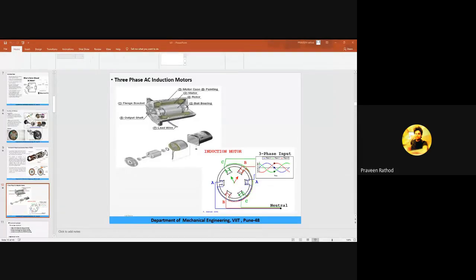Typically a small-sized, high-speed, low-torque motor together with a single-speed, high-reduction transmission can be used. This single electric machine can be used over here. What is it helpful for? It helps in reducing the mass and inertia, so it is not necessary to consider the inertia in the electric machine of an electric vehicle. It can be neglected in electric machines.